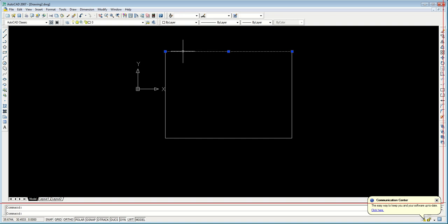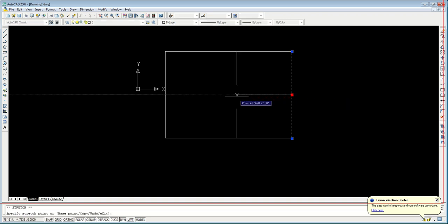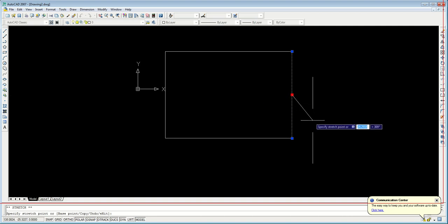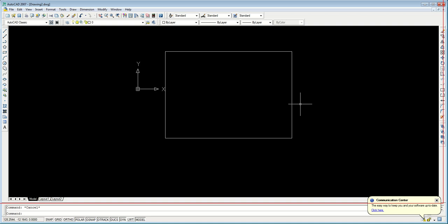Another thing, if I click on the line, this line for example, I will see that there is the center blue box, which is for movement of the line. If I click on it, then you can move your line. Usually, again, we don't use this because you specify a very inaccurate place. So usually we move it using a dimension like this, and we write some dimension accurately, or remove it and go to this place and draw another line. Okay, but this is a facility in the program of AutoCAD.